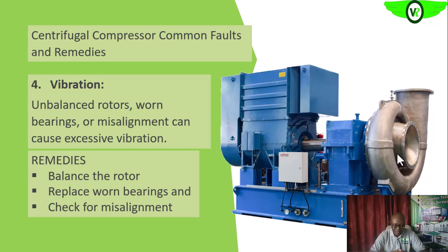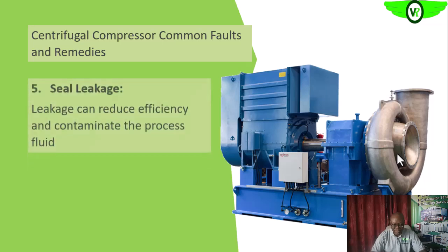are having excessive vibration. Misalignment too, as it tries to overcome the misalignment force, either at the coupling between the gearbox and the electric motor, or if it is direct coupled, or between the compressor and the gearbox. Okay, if there is misalignment, all of these misalignment forces will contribute to the increased vibration, and all of this we also see during the vibration analysis.